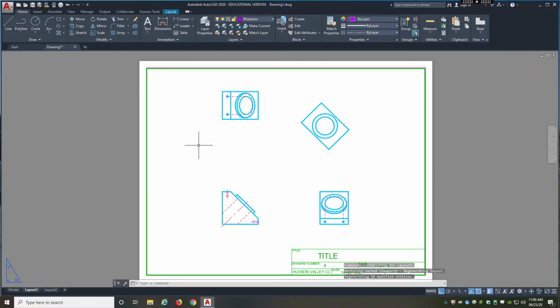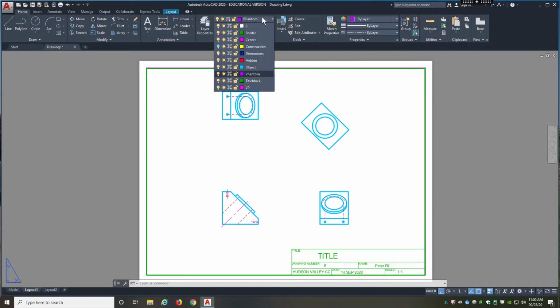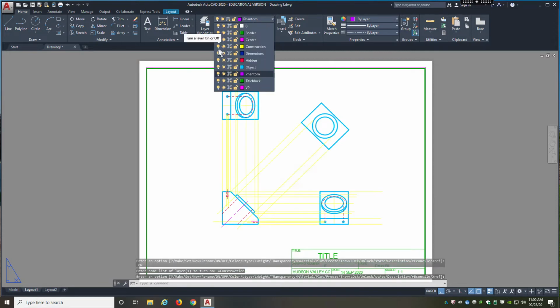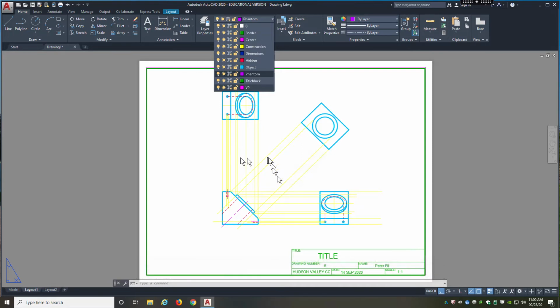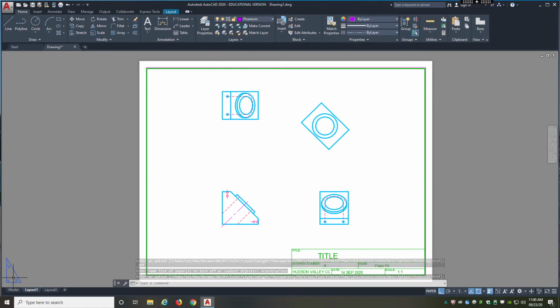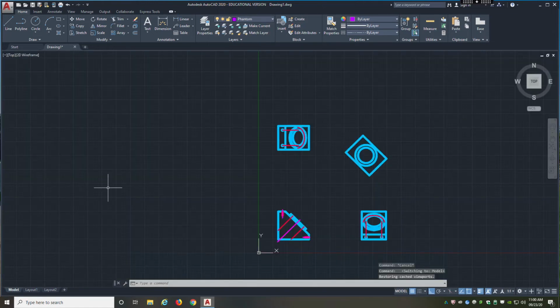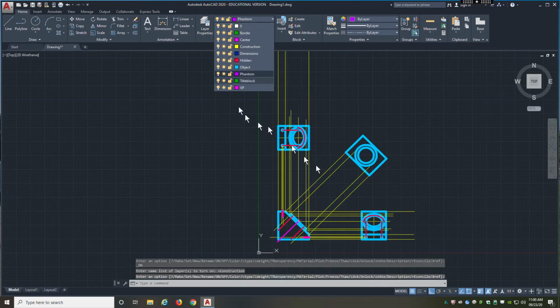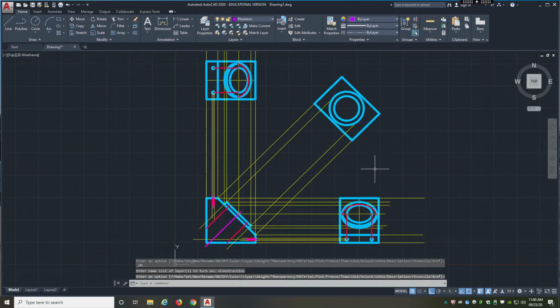And that's using all the miter lines. Again, don't forget to turn off your construction lines because we don't want to see them in paper space. Construction lines are strictly for constructing, and they should not be showing up in your final drawing. So don't forget, turn those off, and then you've created your proper multi-view drawing. So I'm just going to turn them back on just so everyone sees. This is Multiview Drawings.